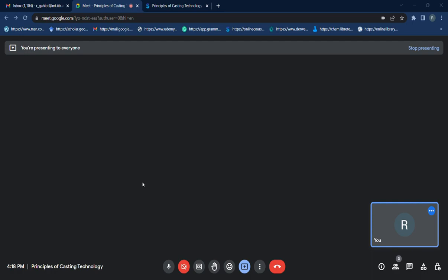But sir, in one objective question I think you told that it is phosphorus and silicon divided by 3. That is for the carbon equivalent. You need to go through the lectures carefully. The carbon equivalent is given by percentage of carbon plus percentage of silicon and phosphorus divided by 3. This is the case of fluidity, and that was the case for the carbon equivalent. Visit the lectures and make proper notes of those, so that will be helpful for you.